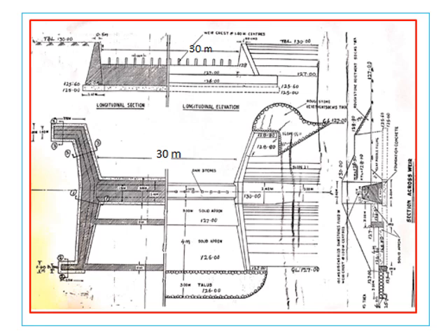So you can fix up the top of the bund onto the sections and decide the earthwork calculations. That is part of the survey work, and you can calculate the volume of earthwork that has to be done for the bund. Also you can calculate the earthwork for the canals. So you can finish off this tank project.